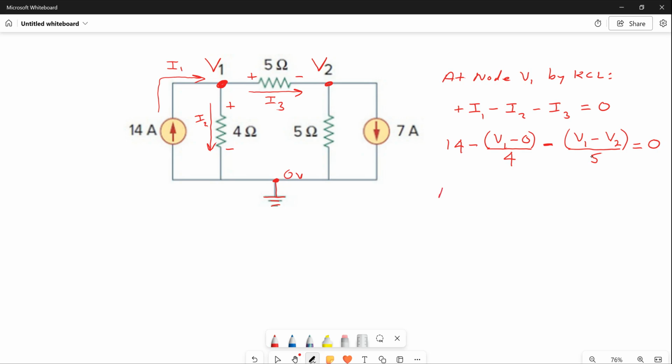When you're looking at node V2, by Kirchhoff's current law, top level equation, just zero in on node 2 now. You have to assign a current here, let's make it I4. Plus to minus now, this current, you know it goes in that direction, that'll be I5. The current source gives you the direction of the current, so it leaves, so it's I5.